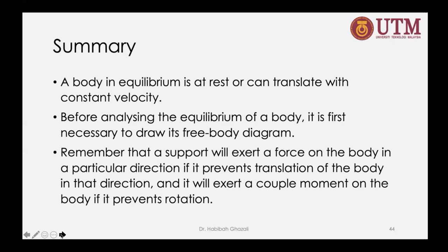So remember that a support will exert a force on the body in a particular direction if it prevents translation of that body in that direction. And it will exert a couple moment on the body if it prevents rotation in that axis or that direction. Okay, so that's for lesson 1.